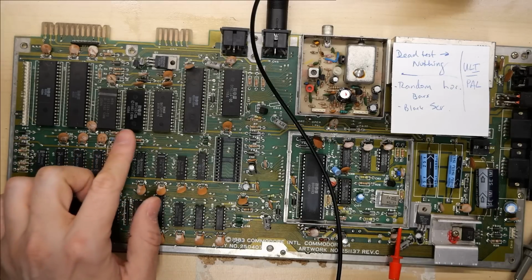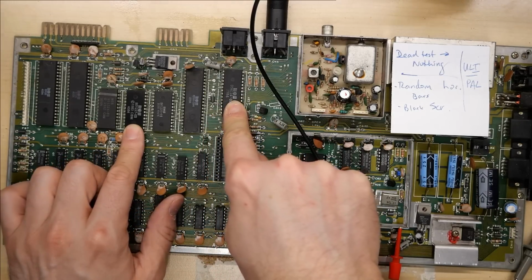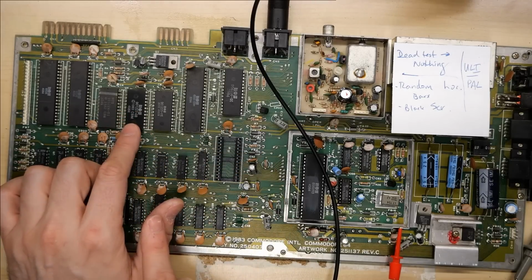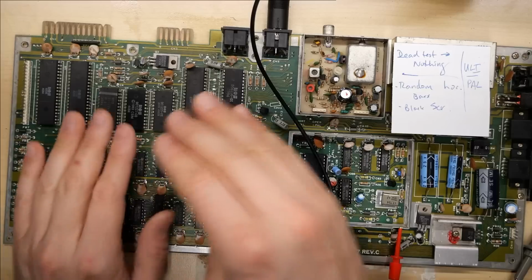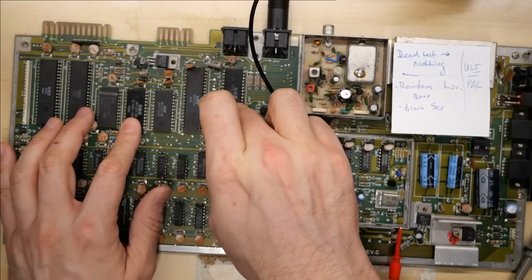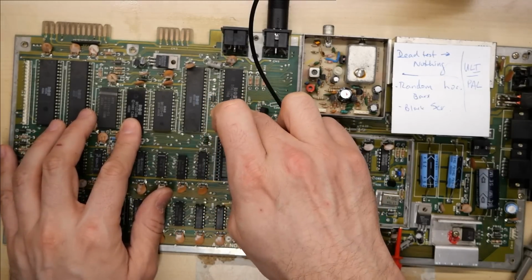Now at this point, I'm going to say that the kernel ROM is bad or the PLA is bad, but I'm actually going to go out and say that it's the kernel ROM that's the problem. And that's because on the oscilloscope, we saw some up and down. It just was all the way near ground. And I'm thinking that the kernel ROM is actually shorting the PLA's output and keeping it down near ground.